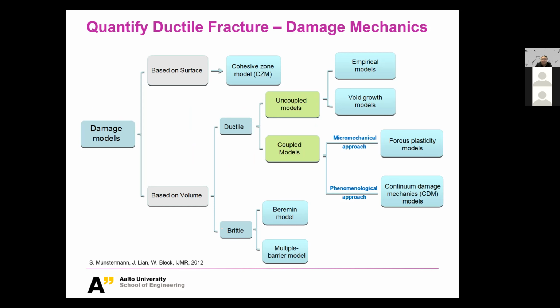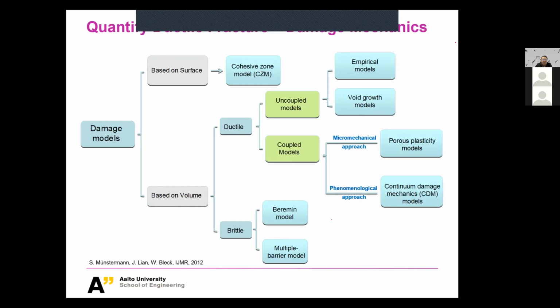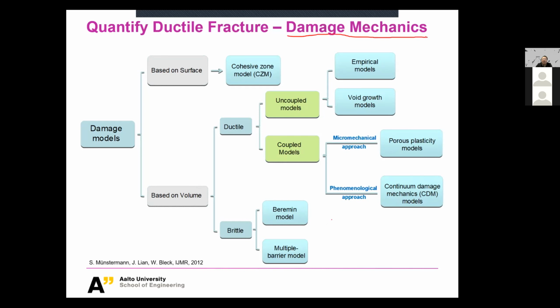And one point before we dive into it, actually different from fracture mechanics. Remember, we learned fracture mechanics yesterday. That is a discipline that we could rather easily use, well established, to describe cleavage fracture. And for ductile fracture, we're using so-called damage mechanics. This is another discipline which has been developed in the last few decades, basically to describe ductile fracture and to predict ductile fracture.